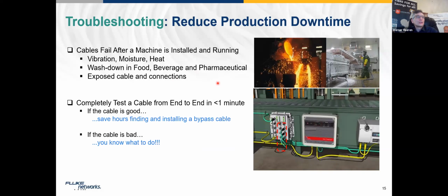So this could harm the cabling and could even stop production if the communication is not working anymore on that cable. Here you see some overflow of chemical products. If that hits the cabling, if it's not properly dimensioned, your production stops. So you need to have the right dimensions, the right configuration of your cabling in place.